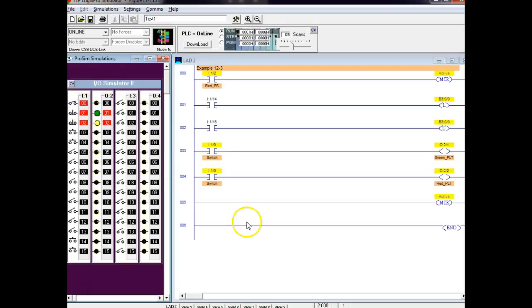Let's turn them on. So here everything's on. I'm going to hit my master. I'm going to take out my master. So what went off was the non-retentive contacts, right? You understand that? The retentive contacts do what? Okay, they are not disabled. The outputs are not disabled.